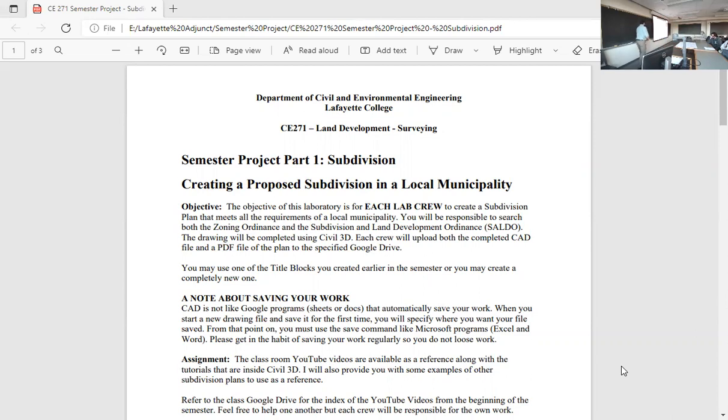And when you tie two roads together, like if this is an existing road and my road wants to tie into it, can I have the curve end right at the road? What do we think? No, we need to have a tangent distance. There needs to be a straight section from center to PC. Then you can have a curve. That distance is spelled out in the ordinance.